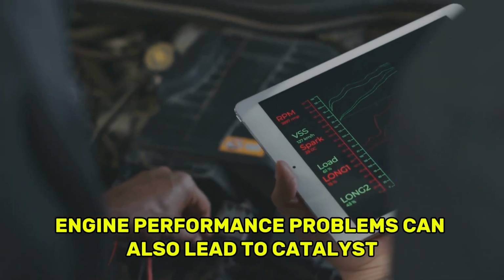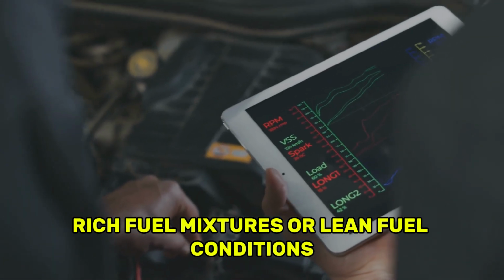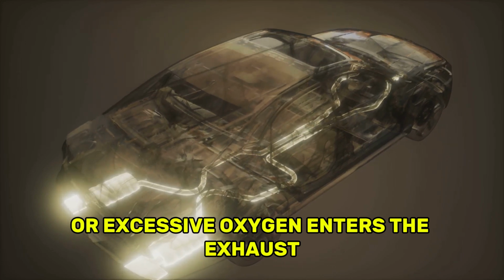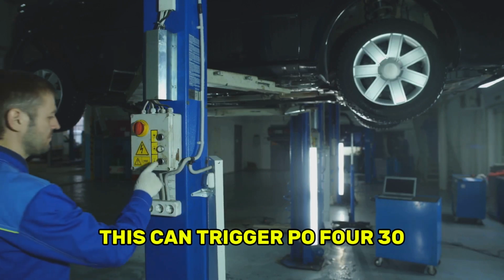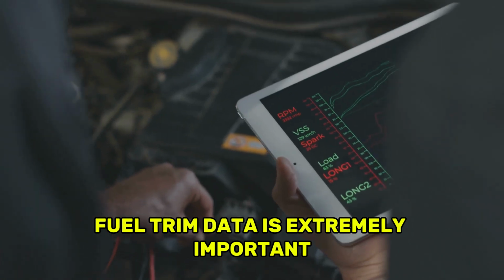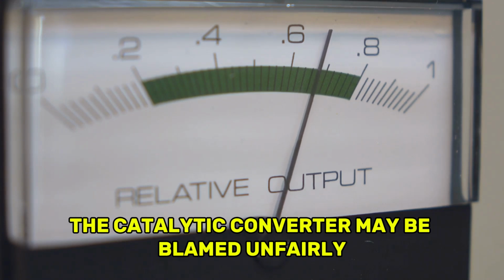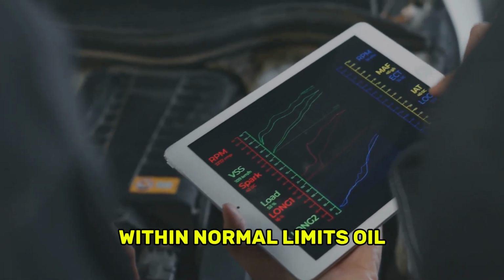Engine performance problems can also lead to catalyst efficiency codes. Misfires, rich fuel mixtures, or lean fuel conditions can overload the catalytic converter. When unburned fuel or excessive oxygen enters the exhaust, the converter cannot function properly. Over time, this can trigger P0430, even if the converter itself is not damaged. Fuel trim data is extremely important when diagnosing this code. If bank 2 is running too rich or too lean, the catalytic converter may be blamed unfairly. Always check short-term and long-term fuel trims to make sure the engine is operating within normal limits.